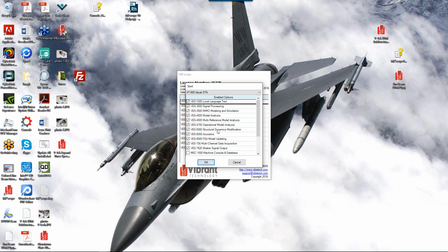So that's the power of SDM, is that it only needs mode shapes, and so we can get them from FEA or we can get them from experiment, and we can do a lot of different things with it. Today we're going to do what's called substructuring. So I'll show you how we can put together the mode shapes from several pieces of a structure, and then use SDM to come up with a set of modes for all the pieces attached together with stiffeners. So that's what we're going to do today.